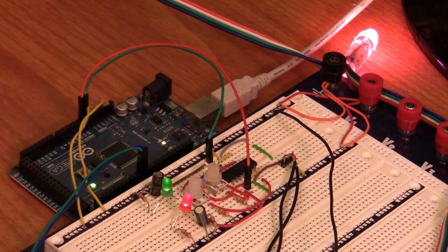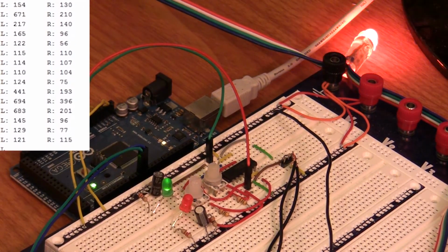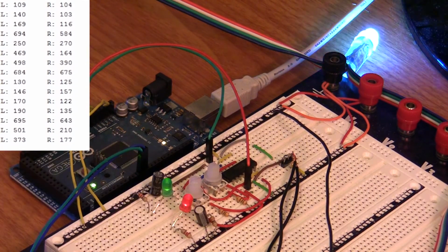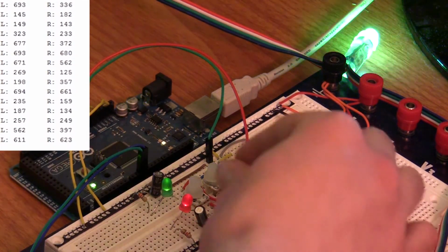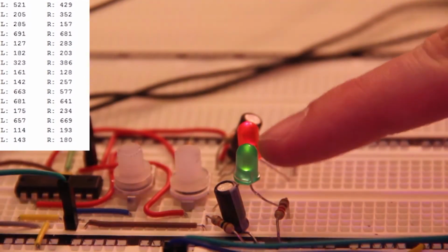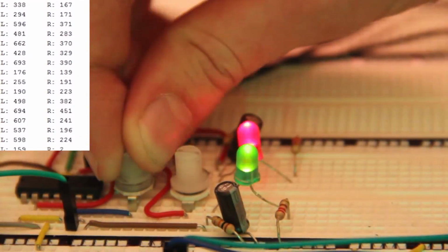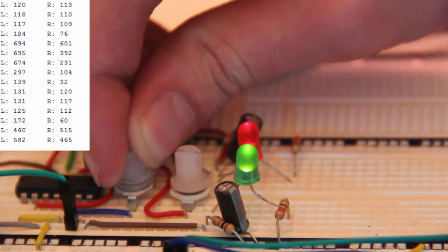So we have our serial debugger running, and we have some music playing now, and we can see it's working quite nicely. You can also tune these LEDs to adjust the rate with which the lights respond to the music. You can make them more or less sensitive by adjusting the potentiometer. So right now we only care about the left channel, which is the green one. By adjusting the green potentiometer, you can see that we can change just what the threshold is for them to respond to the music.